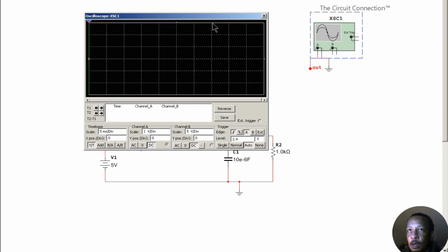Okay, so I'm expecting to see 2.5 volts at the top, and I have this scaled for 1 volt per division, so I got 1, 2, 3 volts maximum, so that makes sense to use that. And then my longer of the two transients is 50 milliseconds for a time span. So as long as I have enough to show 50 milliseconds here, that'll be appropriate. And I have this time base set at 5, so I have how many divisions? 1, 2, 3, 4, 5, 6, 7, 8, 9, and 10. 10 times 5 is 50, so that should be perfect for this circuit setup.